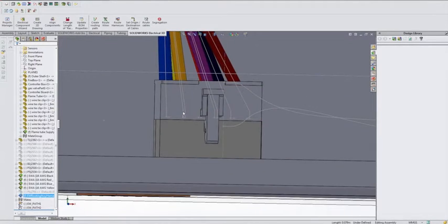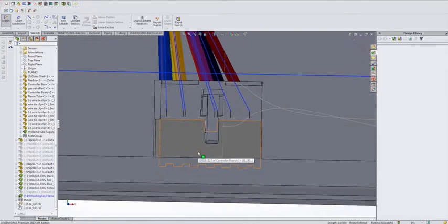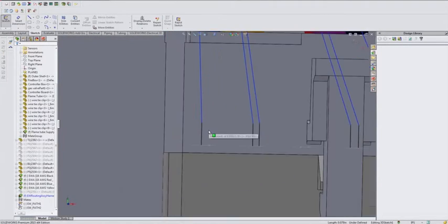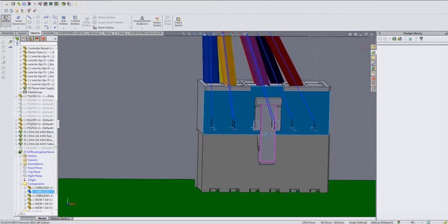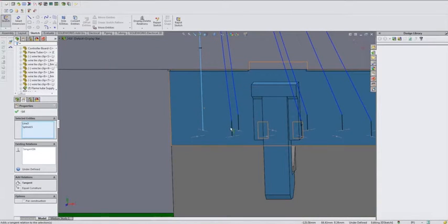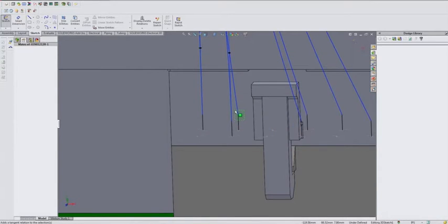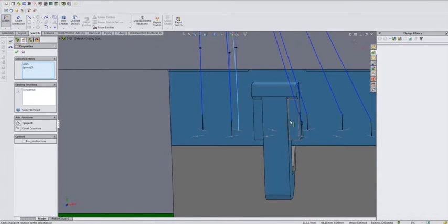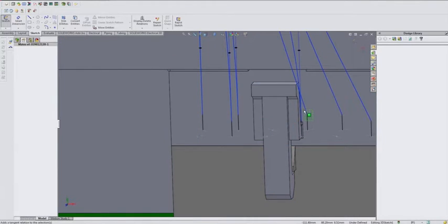But you can actually edit your route. So once again, this is using the SOLIDWORKS routing engine, and I can simply add in some tangencies here. So I'll go ahead and rotate to get myself in a little bit better position, and then I can simply add in some relations, right? So I'm just adding in some tangent relations. Numerous ways to do this. You can window select as I'm doing here, or you can do a control select. The main thing is you're just selecting two things at once, right?